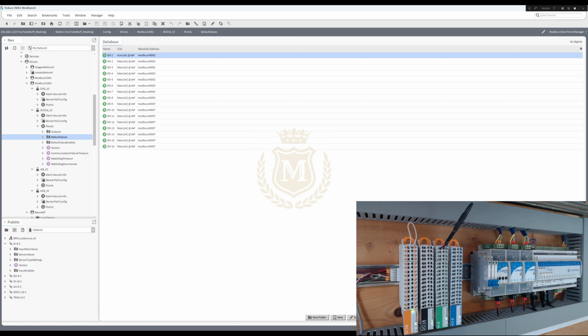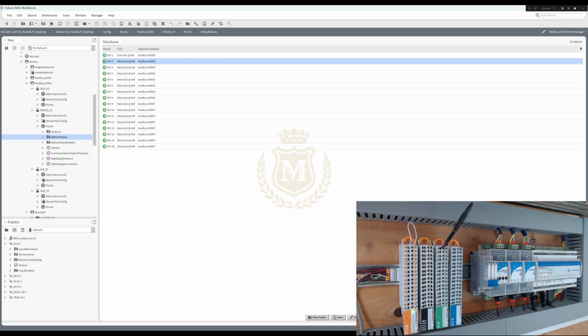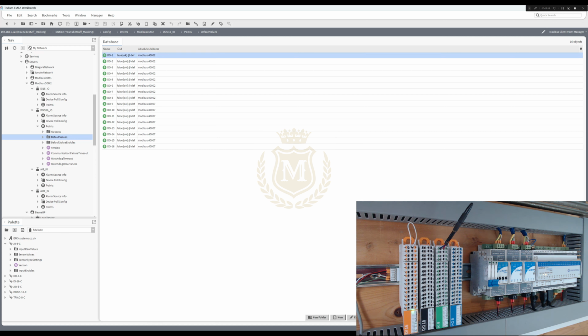If we do lose the Modbus communication, it will put that output to true. Normally you'll just have them all set to false, but in case of some equipment that you want to be on constantly, when you've lost your controller or the network to your I/O modules, you can set these to different values.